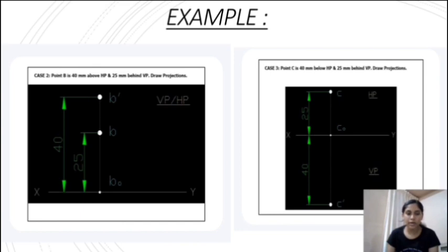Then you get a 25 mm line, and then from that 25 mm line you can give 15 mm and again 90 degrees and press enter. You could see 25 mm and 40 mm lines. For visibility of dimension, you can use smart dimension.